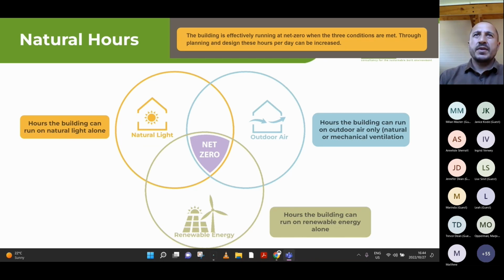But what I'm trying to say is that mechanical ventilation goes through filters and all those things. You can't have a filter on every single open window. Yeah, but we're not talking about opening windows. We're saying use that mechanical ventilation system that is there. The only difference is that your fresh air can enter the space directly and doesn't have to go through a fan coil unit. That will mean that the fan must be running. That'll mean the chiller must be running. This is with the assumption that windows are closed and you are just using the same fresh air system. Okay, I was meaning actually opening windows, but that's cool.